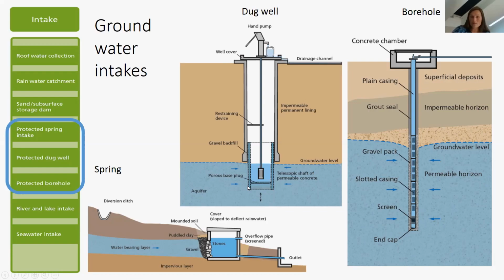For a borehole, steel or PVC pipes are normally used for lining the well walls, and the well screen holds back the sediments but not water from entering the well. If you use PVC pipes for lining, this can be slit to create fine cuts, acting as a barrier for sediments. You see here below.